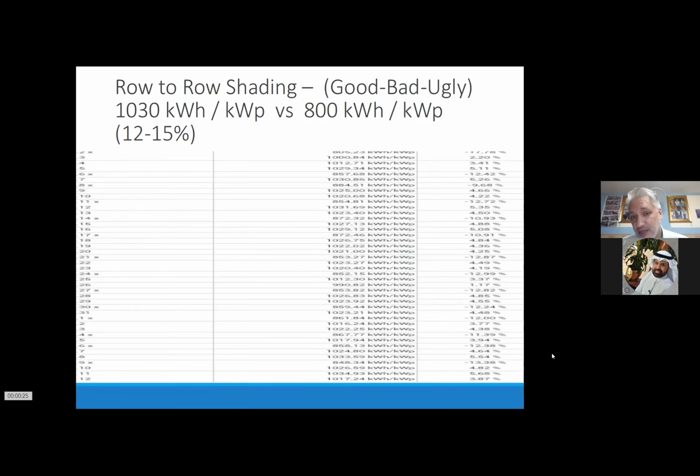So you end up with 900 or 875 kilowatt hours per plant because the shaded strings, via the mismatch, are destroying the good strings. So when you encounter that, you should install shaded strings to shaded combiner boxes. So that means all the shaded strings have the same problematic issues, because when the shaded strings take over the good strings, then the inverter will change also the output. Depends how big, if it's a 500 kilowatt, 1 megawatt or 2 megawatt inverter.